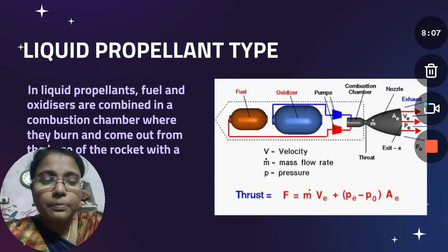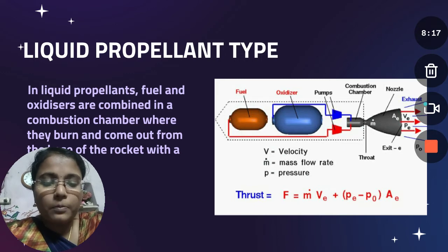The common liquid rocket is bipropellant. It uses two separate propellants, a liquid fuel and a liquid oxidizer. These are contained in separate tanks and are mixed only upon injection into the combustion chamber. They may be fed to the combustion chamber by pumps or by pressure in tanks.